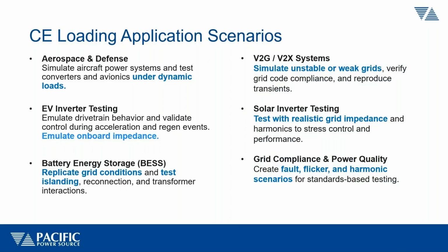So again, there's a multitude of application industries where loads can be used, especially in aerospace and defense at higher frequency buses. You can create load conditions and load scenarios to test your power distribution buses and your power sources on the airplanes or on the equipment. EV inverter testing, especially bidirectional chargers and EV motor drives that can generate power in both directions, can be tested.